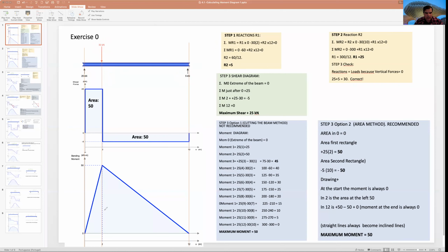After you have your diagram, you can start doing your bending moment. Again, you just need a line that shows you what values are positive, above 0, and what values are negative. Also, dotted lines where the beam starts and where the beam ends, and because this is a very easy one, we only have another dotted line that shows the place where we have the only force that is 30. Reactions are in line with the start and end of the beam, where we don't need additional points.